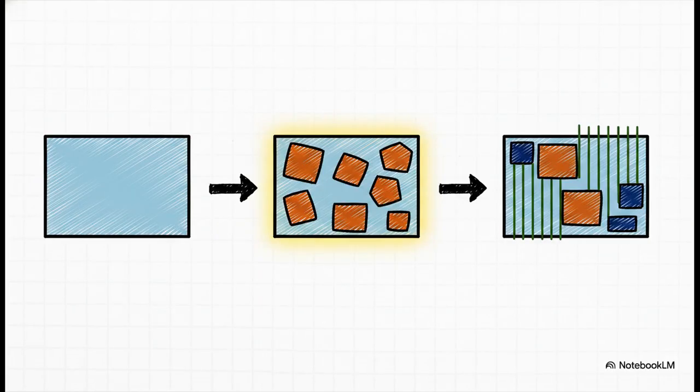You know, the tiny details of how you actually build the chip matter a lot. And the specific technology we're looking at today uses a process called a gate cut first integration. All that means is that those gate cuts are put in place pretty early in the manufacturing process. And that choice has a huge impact on exactly how these stress effects play out.